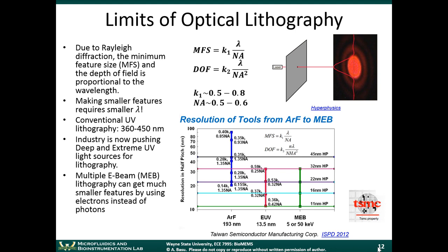Standard masks are made from a glass plate, which is transparent to ultraviolet light, and then on top of that you have these patterns of chrome, metal patterns. Basically, the opaque regions, the metal regions, don't allow light to pass through. Okay. So those masks are pretty robust. Even if they're contaminated with photoresist, you can clean them just by putting them in acetone.